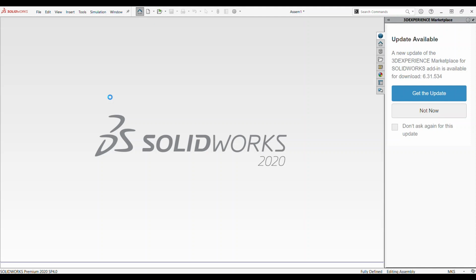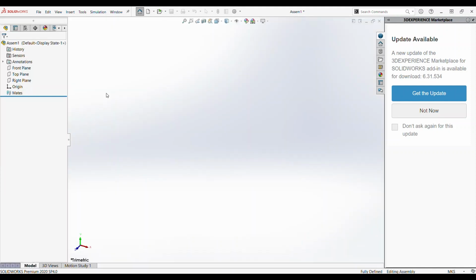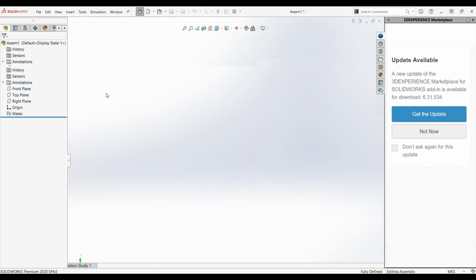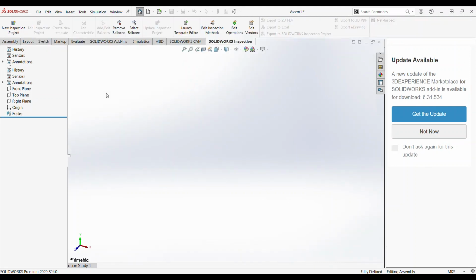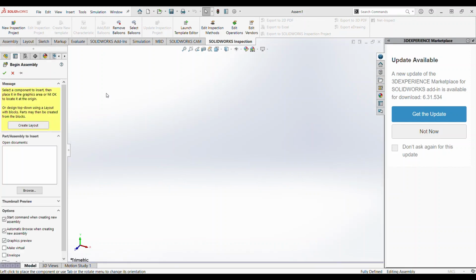Then SolidWorks gonna ask what parts we wanted to assemble, and based on our previous drawing we're gonna select the folder. So you see automatically it shows the assembly drawing and the specific folder, because previously I have done this folder, so SolidWorks automatically selects this folder, but if your folder is somewhere else you can select from here.